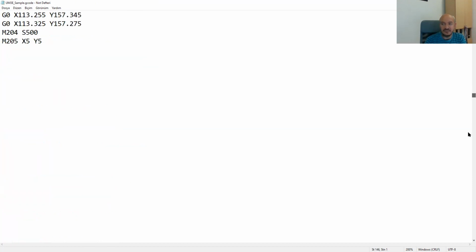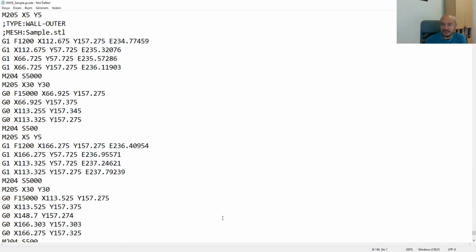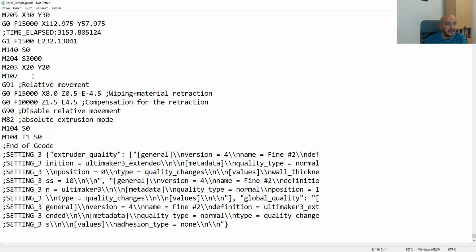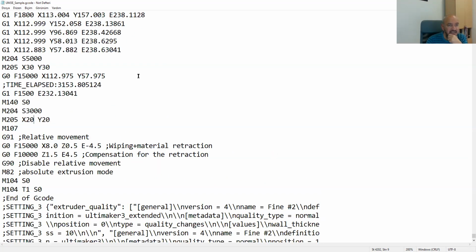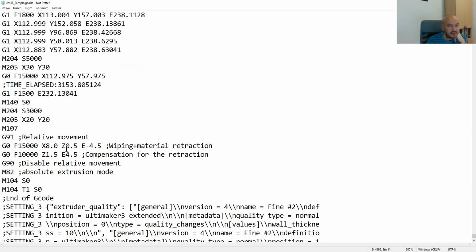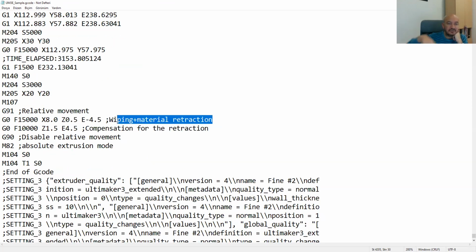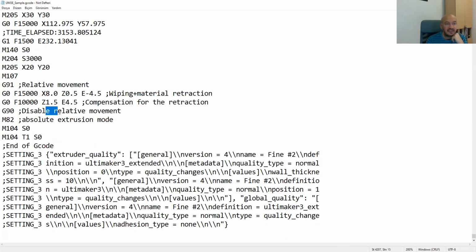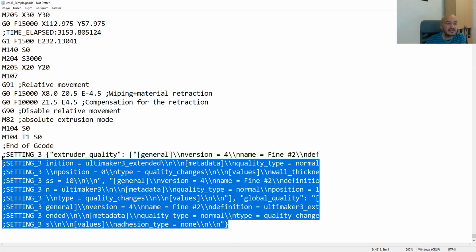Now I'll jump to the last part of this Gcode file. Yeah, I think that is here. Around here, the printing is over. It's doing some retraction, and then it is setting the temperatures to lower values. It's wiping the material around your spool. It's doing some more retraction, disabling all the stepper drives, and then setting this temperature to 0, as you see here. And this is the end of the Gcode file.